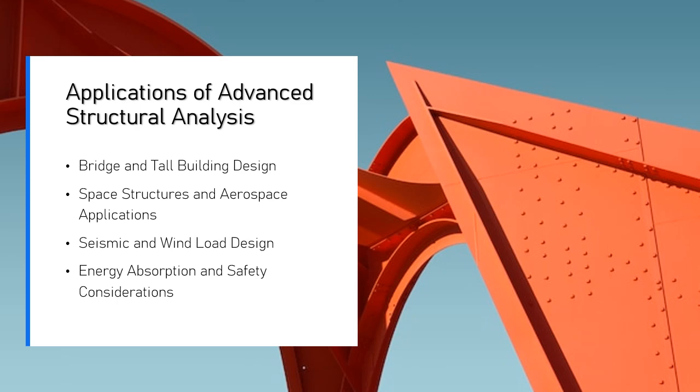Structural engineers used advanced finite element analysis (FEA) tools, such as ANSYS, to simulate load distribution and stress behavior across the bridge. Nonlinear static and dynamic analyses were performed to account for the complex interactions between the deck, suspension cables, and towers.